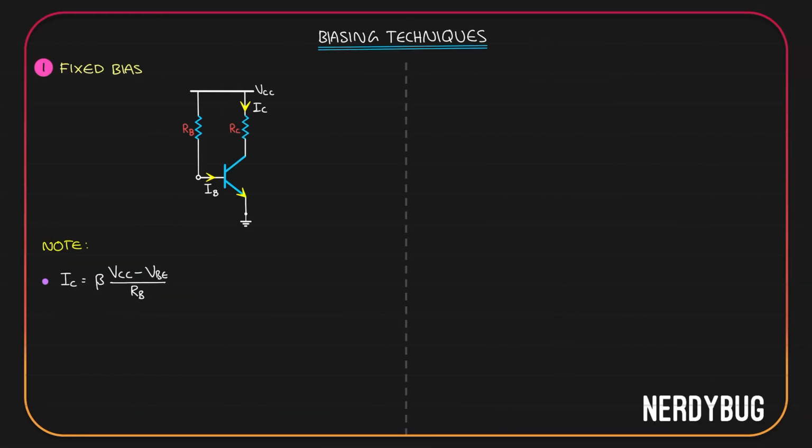Now, there is an important thing that we have to note regarding fixed bias. We saw IB is VCC minus VBE by RB, and that gave us collector current IC is beta times VCC minus VBE by RB. Or basically, the collector current IC depends on beta. But the problem is, beta is significantly influenced by temperature.